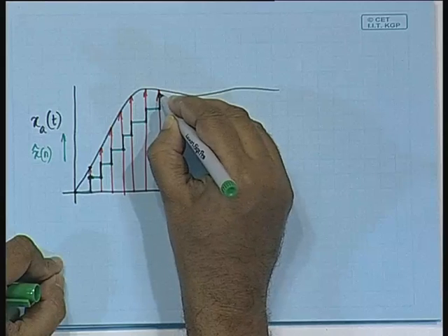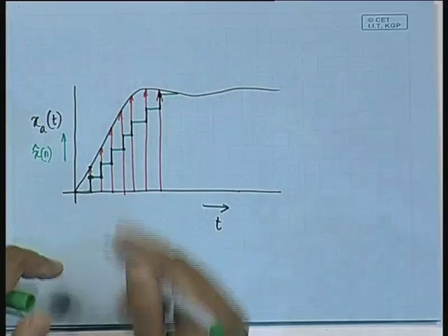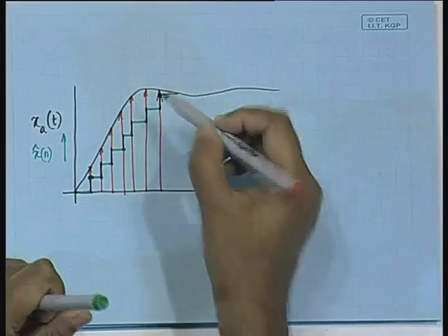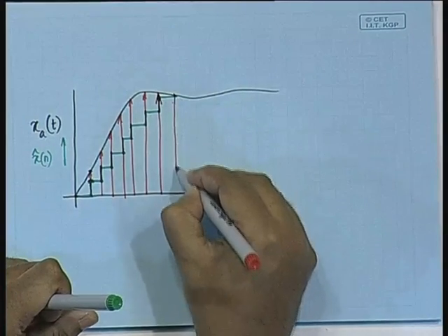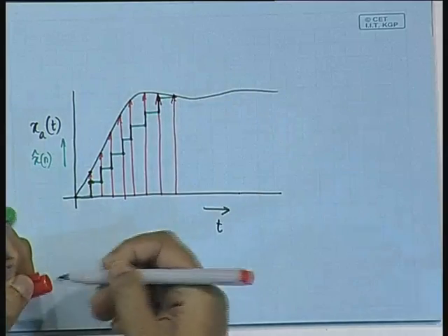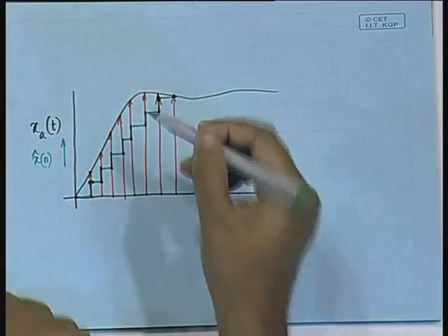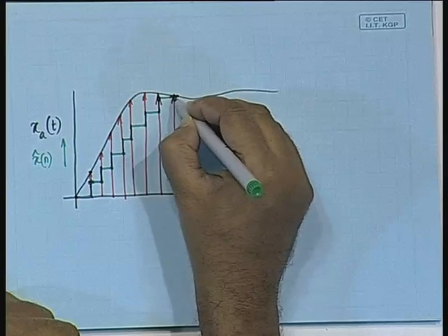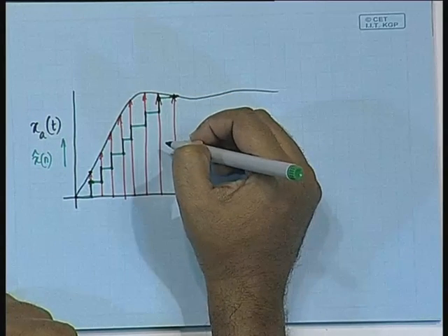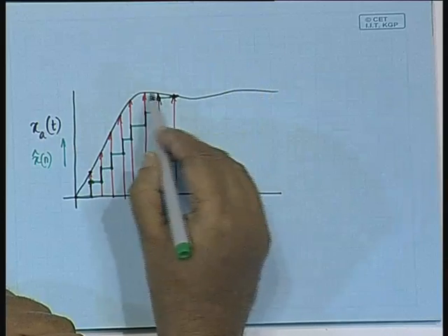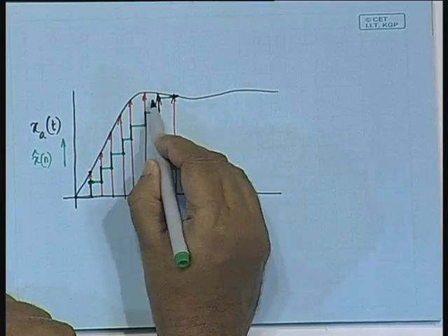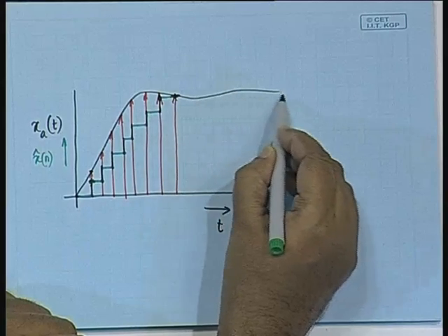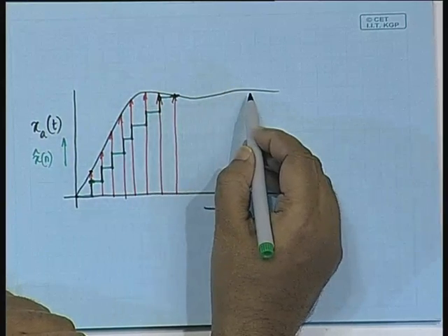Only when we come to the next sample, say the next sample is taken at this instant, can we see that there is scope for a changeover. Now the estimated signal can be higher than the incoming signal, because there is some droop that this characteristic is indicating, or you can say it more or less has a uniform value.